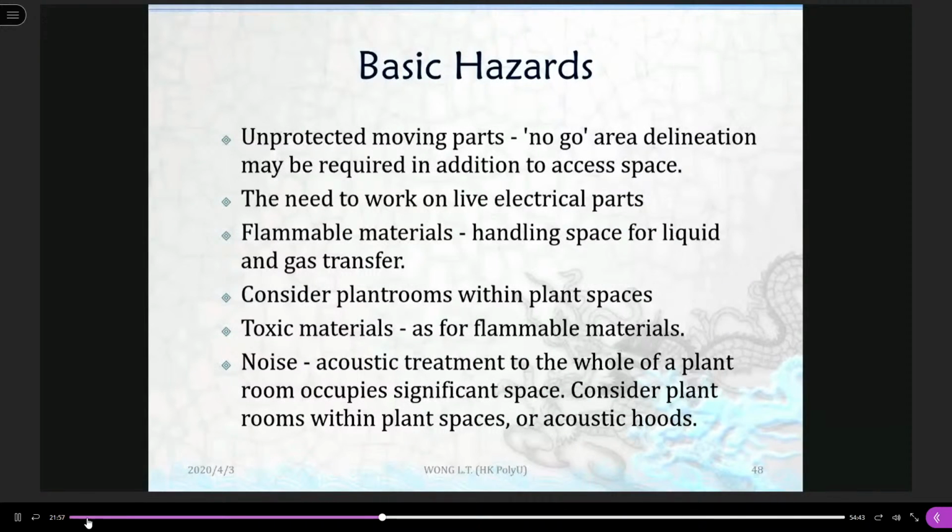I think there's one example recently I found in some non-industrial premises. Recently some people tried to produce hand washing gel using alcohol. They used a very big pound of alcohol, put inside the shopping mall, open space, and tried to mix it. There are two concerns. One is the storage; the storage cannot be that huge because of fire. Another, more important, is the processing risk for fire, because you try to mix something not in industrial provisions.